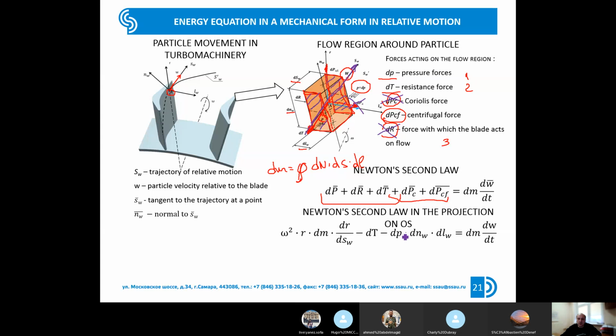That's why we can write the pressure force from this side as P multiplied by the area of this side of the brick, equal to dn multiplied by dl, and the same from the opposite side of the brick: P plus dP multiplied by dn dl.